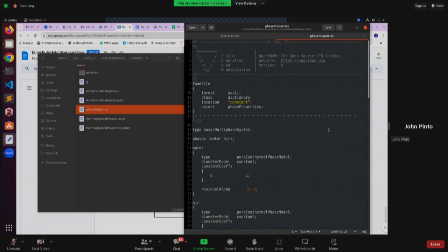In this water and air system, as sir gave an example, wherein you are passing air from some perforator, then by experiments or from the perforator size, you will know the average size of those particles. So that will be your input parameter. That is a parameter that is input and used by the model to calculate the various forces like drag, lift, and all those things.